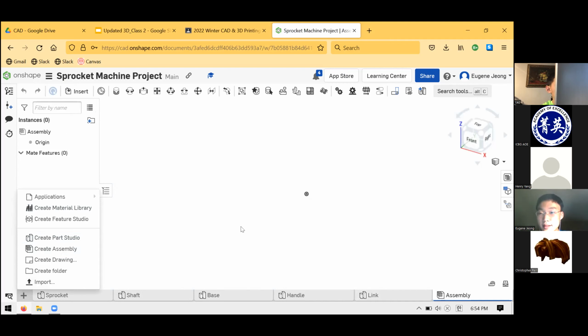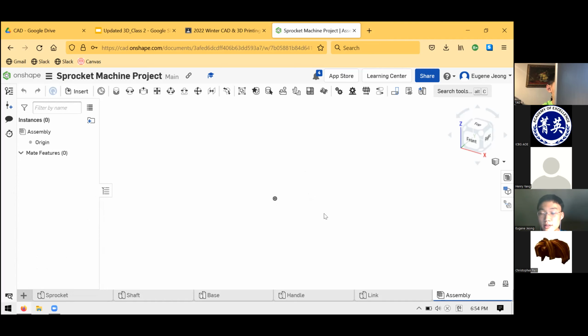Why does it not fillet on both sides? You need to select every edge that you want to fillet, unless you select a face, in which case it will automatically select every edge that is a boundary. I'm not sure if it does this in Onshape, but in a lot of other CAD programs, if you select a face, it'll automatically pick all the edges. But I say don't worry about the link right now. If you want to do that, you can do that later.